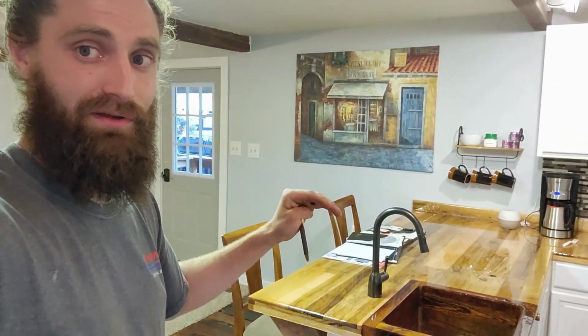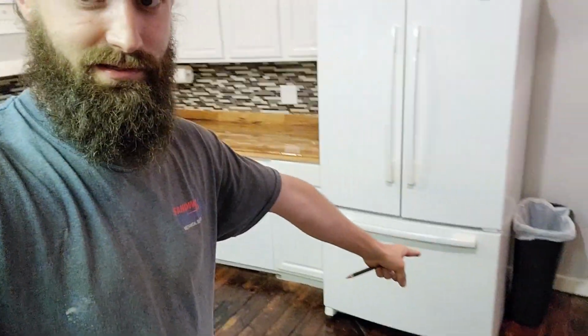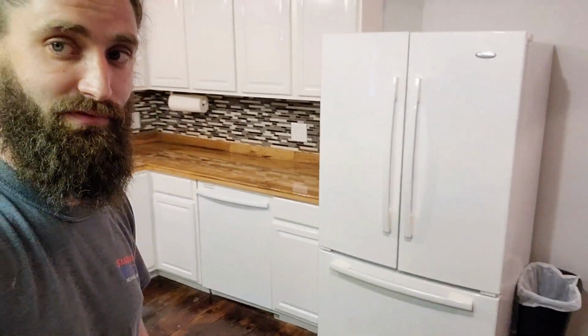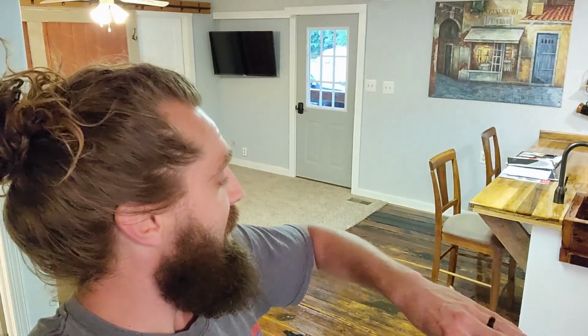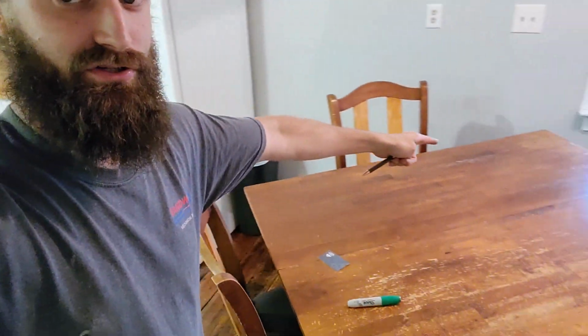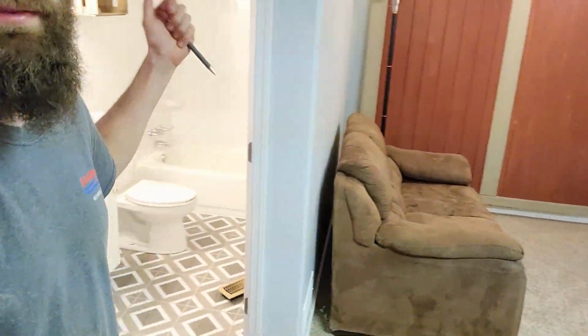Do not put your supplies in front of the refrigerator. Do not put your supplies in front of the dishwasher, and do not put them in front of the oven, because when it comes time to replace those appliances, they're just going to get smashed up, and you're really going to make somebody unhappy. I can say that. I've been in homes where they have stuck a floor register either right in front of an appliance or right in front of a door, and it's all smashed in. And what good is it doing anybody at that point? So be mindful of where you're sticking them.